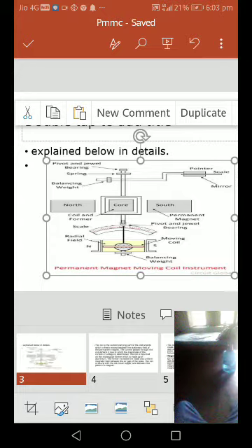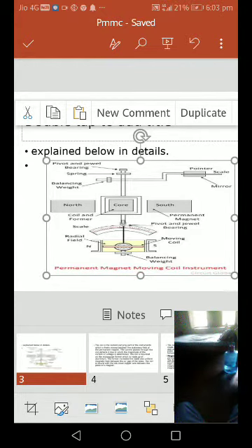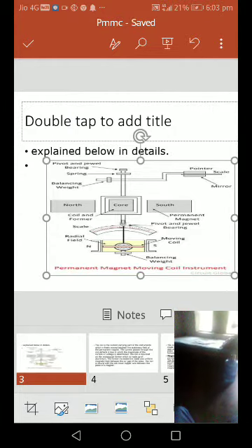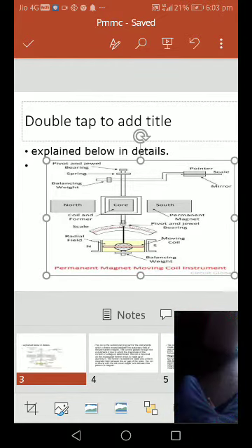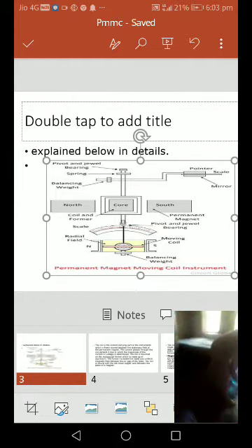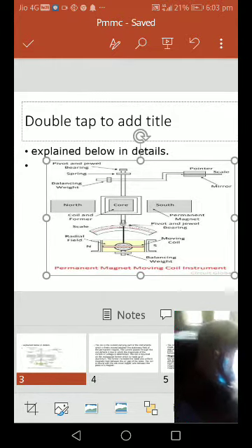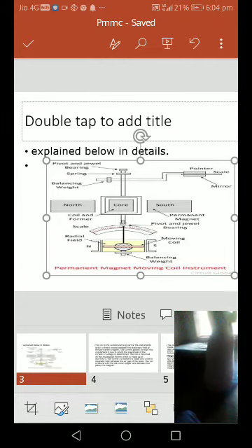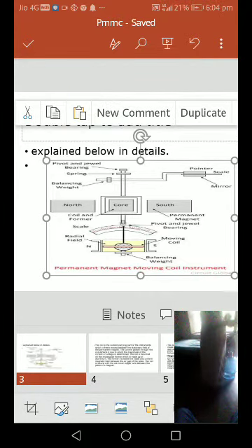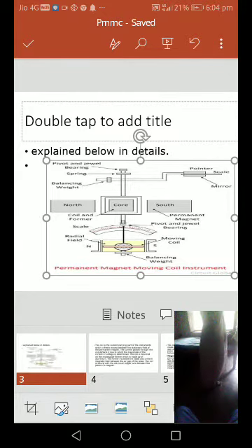Below we have the controlling and balancing weight for the coil, and a spring is provided. It has an electromechanical construction, with the coil, pivot and jewel above, the spring, and the balancing weight. A pointer points to the scale, with a mirror on the device, along with the permanent magnet and the pivot and jewel bearing.